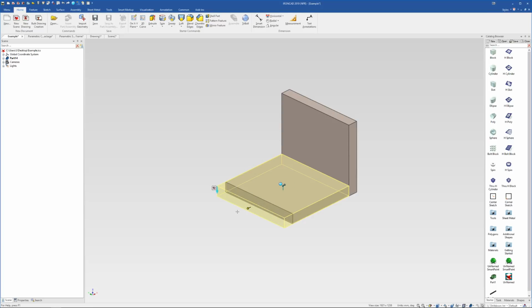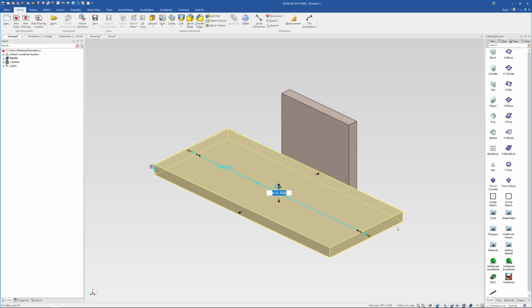Now you can see if I hold down the control button, they're actually going to snap to precise sizes. So instead of snapping to just a random dimension, if I'm not holding the control button like that, they're going to snap to increments of 10 mil. When I'm holding the control button, they're always snapping to those increments. It always ends up being an exact amount. That's just worth noting. So you can see as I'm sizing here, it's only going up in 10 mil increments. It won't let you go 49.99 or anything like that. So you can just see how that adjusts there. So that can be a useful tool.